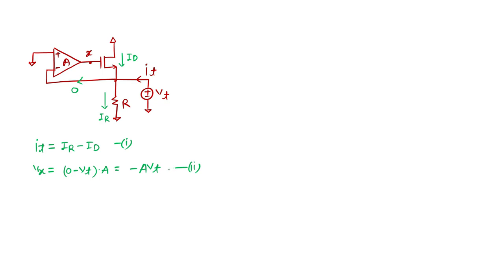Now the thing I want to calculate here is ID. I have told this many times. The expression of ID for any particular transistor is GM VGS plus GMB VBS plus GDS VDS.